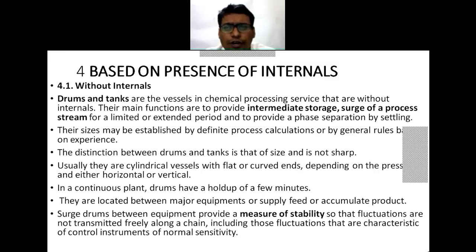When you talk about a drum, the fluid comes into the drum, that is your flash drum. Fluid comes and instantaneously it leaves the vessel. So that terminology is preferred in the industries. The residence time of the process fluid in case of drums is less as compared to the tanks. In tanks, the holding time is more in comparison.